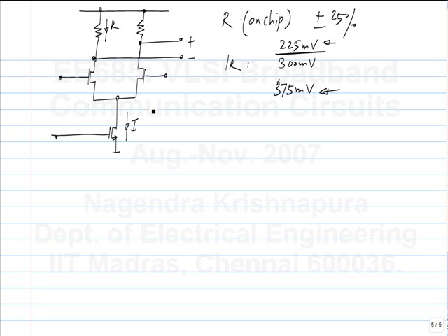Also, it addresses only this issue, it doesn't address the other issue. If the variation is very large, you can have a huge swing. The only way to design it in that case is to leave enough margins everywhere. So that's a waste. That eventually means that the minimum supply voltage you need to operate this circuit will be some value, whereas by a more optimal design you could have reduced it to a smaller value. So the other suggestion is to actually measure the output and adjust the current.